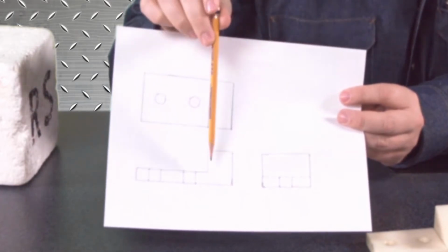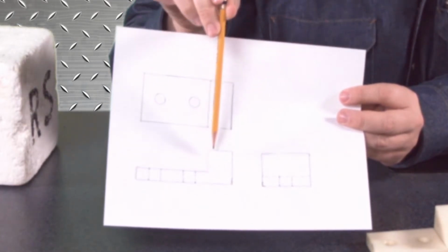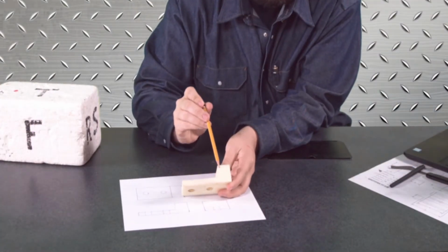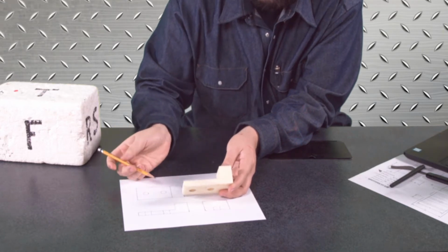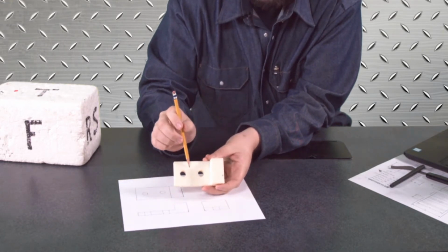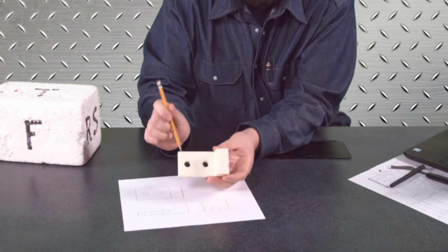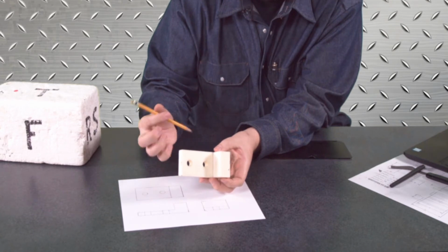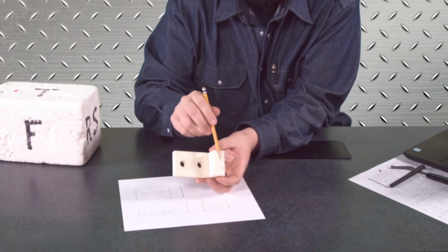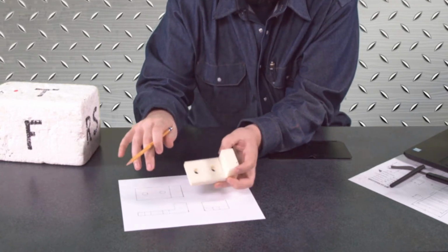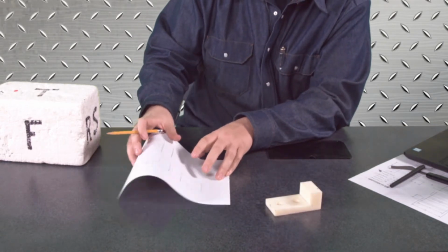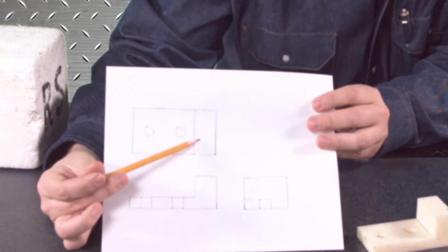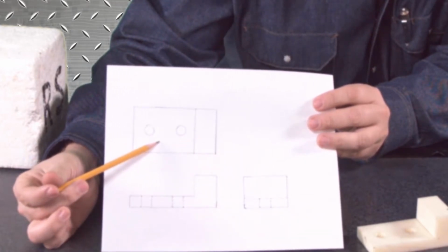So with prints, we have our lines, vertexes, and planes. Each plane being one of these whole flat surfaces right here. And every time there's a different plane, there'll be an object line. So when viewed from the top, you can very easily turn this to the side a little bit because it's a 3D object, and you can see that there's a break right here. But if you were to just draw this flat, you need to add an extra object line right here to let you know that this is one plane and this is another plane, all right?